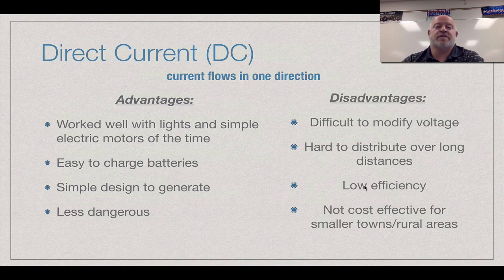And that's what Niagara Falls came down to also. They wanted to build one big power plant using the falls to generate electricity, and they wanted to distribute that as far out as they possibly could. So with a single plant at a single location, the only thing they could really use to make that work is AC current. For DC current to work to power a large area, you would need multiple power plants, all spaced a mile, 2 miles apart, and so forth, to power smaller areas.